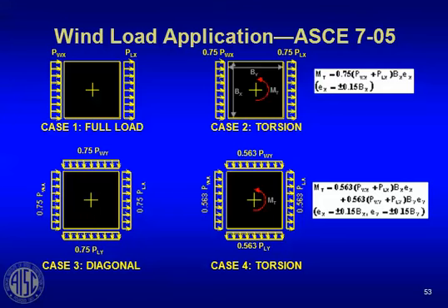That's load case 2. Load case 3 covers the case of a diagonal wind, because we know the wind isn't always just going to blow on the orthogonal principal axis. You could get a quartering wind that might control a corner column or might control some other part of the lateral load frame. We say you're going to apply the load simultaneously in two orthogonal directions at 3/4 of the value, and that's the same as kind of putting a diagonal wind load on there.